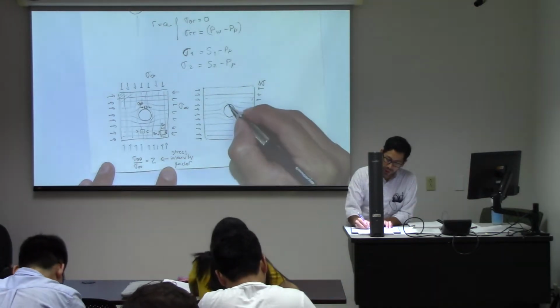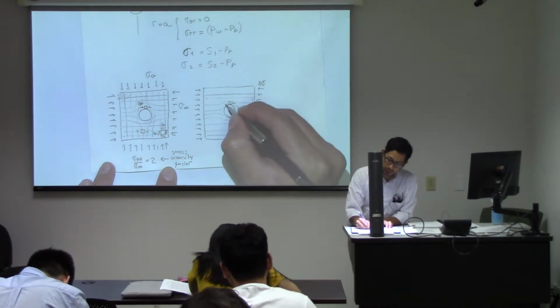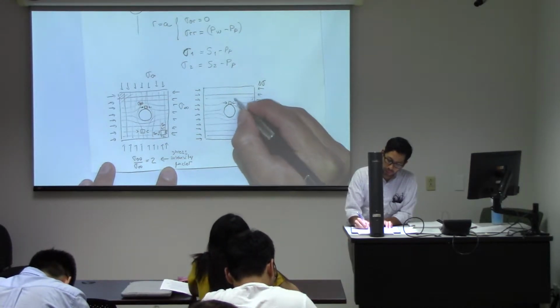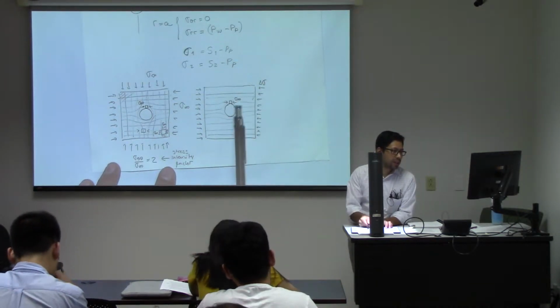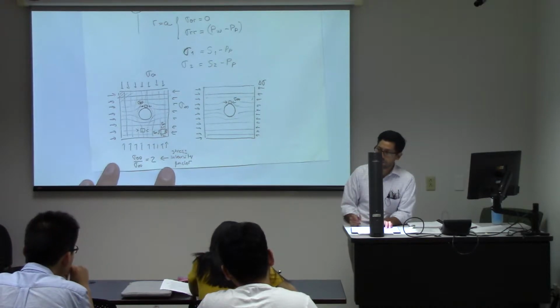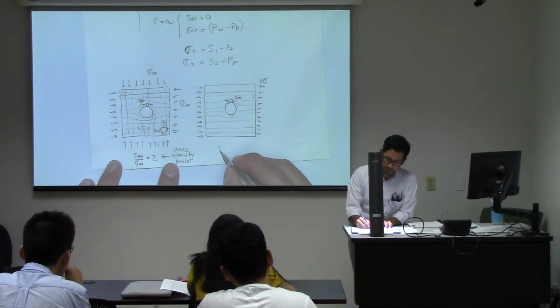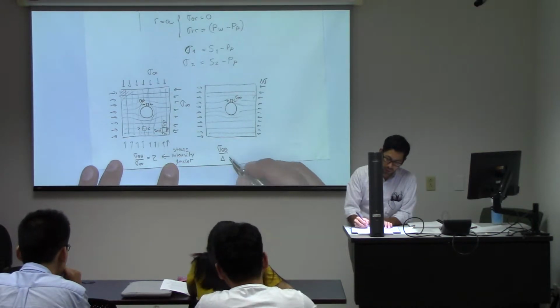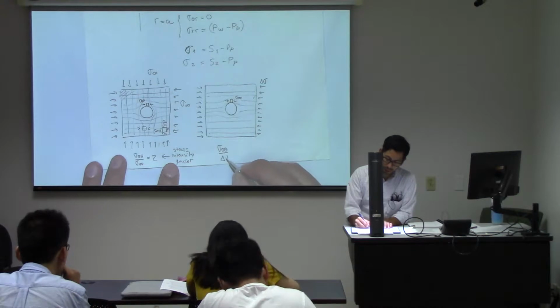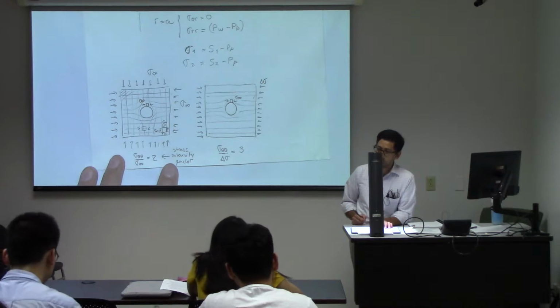Now, if we look at stress right around here, do you think it's going to be bigger or smaller than before? I'm going to compare the sigma theta theta to the stress in the far field. It's going to be bigger, and it's actually going to be equal to 3. And you'll get that too from the Kirsch equation.